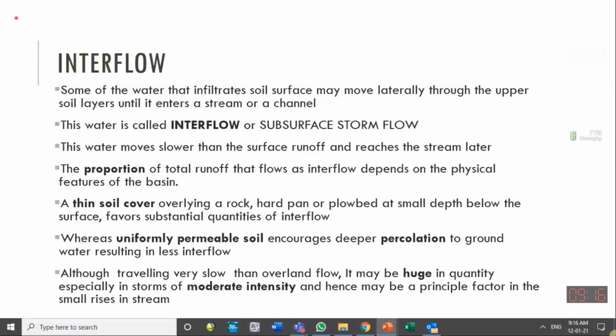So below the water table, we have higher pressure. The pressure rises the same way as static pressure rises in tanks. At the water table line, at the top of the groundwater surface, we have zero pressure. So below that we have positive pressure, above that we have suction pressure. Okay, so that is how we identify that this is a water table. If we put a piezometer where we have the same pressure as atmospheric pressure, we say this is a groundwater table point. If we have many groundwater table points, we can make a groundwater table surface.